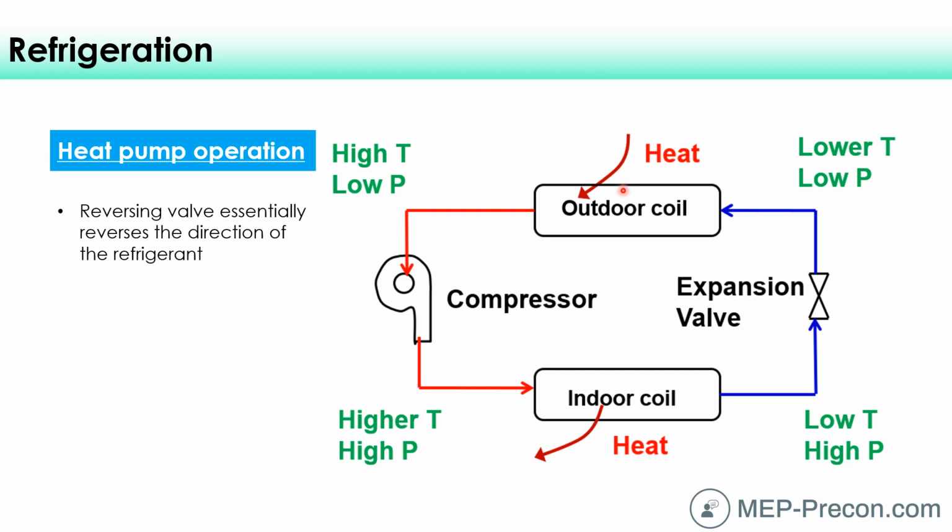And so at that time we usually require an auxiliary heater, just an electric heater within our air conditioning unit. And that's just kind of like a toaster coil type element that just heats up, gets red hot, we blow air across it, and that is how we achieve heat at that point to heat the space when it's really, really cold outside.